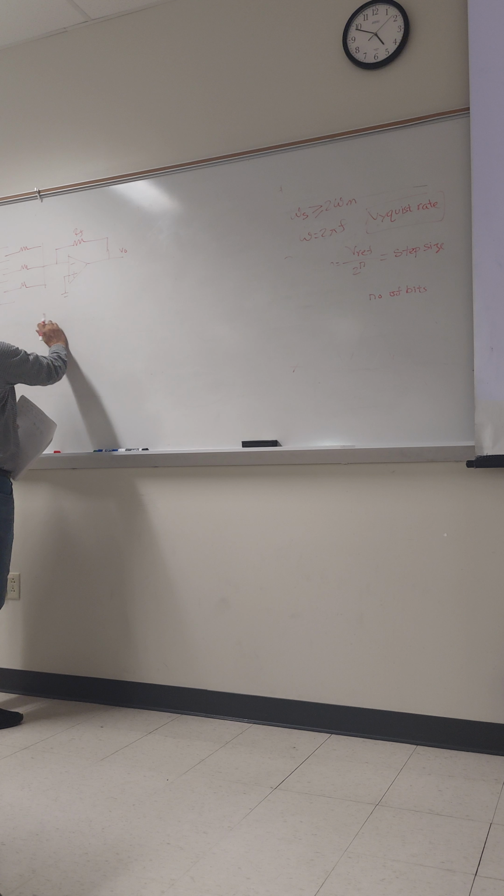For example, this one, then we give it to the op-amp summing amplifier, right? The value of this resistor will be inversely proportional to the binary weight. Why? So that we can represent the digital input accurately, with each bit contributing a value proportional to its weight. So that was the reason.